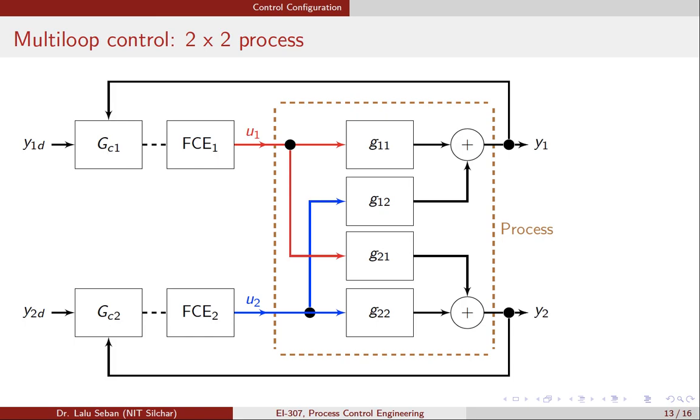Now, what are the disadvantages? Definitely, the investment should be high because we require more controllers, more wiring, more equipment. The initial investment will be high. That is one of the main disadvantages of decentralized control. But considering the advantages, decentralized control has an upper hand over centralized control in the process industry.